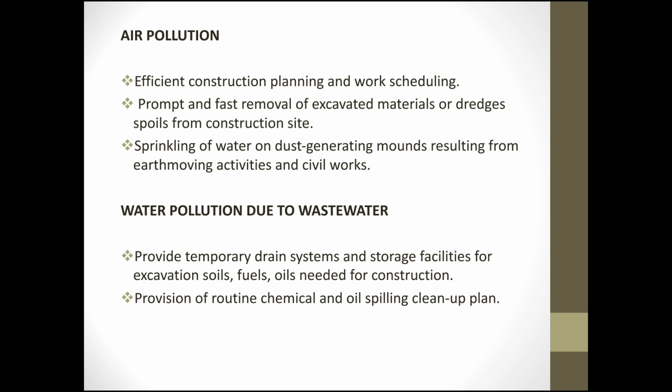Air pollution: efficient construction planning and work scheduling, prompt and fast removal of excavated materials or the dredge spoil from the construction site, sprinkling of water on dust-generating mounds resulting from earth moving activity and civil works. Water pollution due to wastewater: first, provide a temporary drain system and storage facility for excavation soils, fuels, and oils needed for construction. Second, provision of a routine chemical and oil spill cleanup plan.